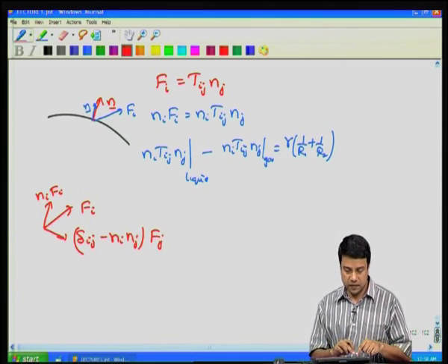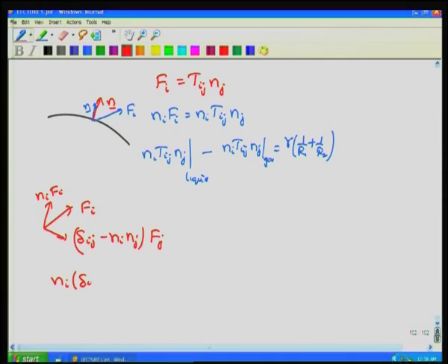You can see that if I take this and dot it with n, I will get 0. Ni times delta ij minus Ni Nj gives me Nj minus Nj times Ni Ni, which is Nj minus Nj times n dot n, and n dot n is 1 because n is a unit vector, so this is 0. Therefore, this has no component along the unit normal, it is always perpendicular to the unit normal. So, the component of the stress in the liquid perpendicular to the unit normal, or the tangential direction in the liquid phase, has to be equal to 0 at a liquid gas interface.